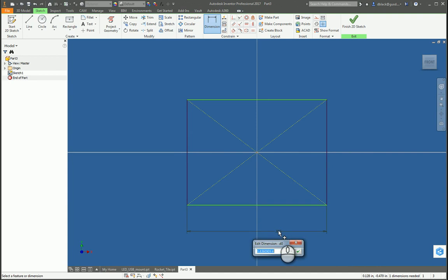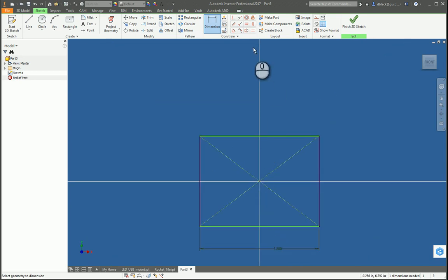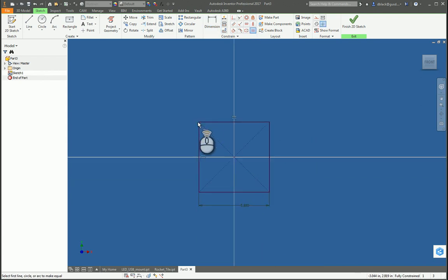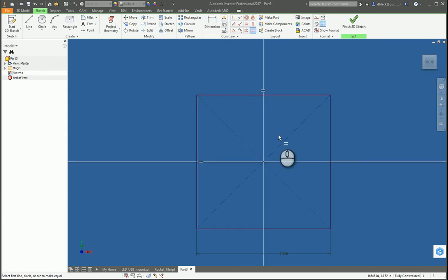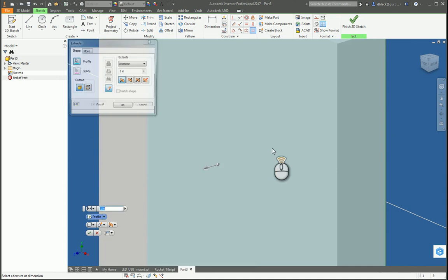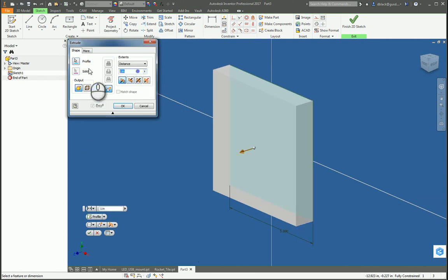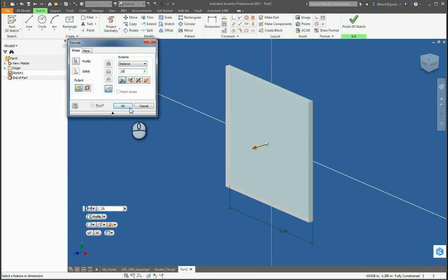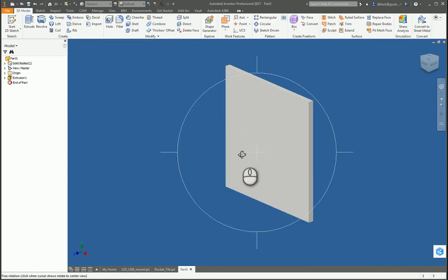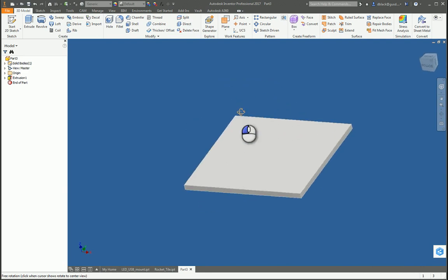Our actual mosaic tiles this year are a little shy of 6 inches. They're measuring closer to 5.88, so I'll go ahead for that. I'll zoom it out, and I'll just give that an equals constraint on the sketch from the side to the top because it is a square mosaic tile. I'll go ahead and press E for extrude and bring that out 1/4 of an inch, 0.25. That matches the thickness of our actual mosaic tile.